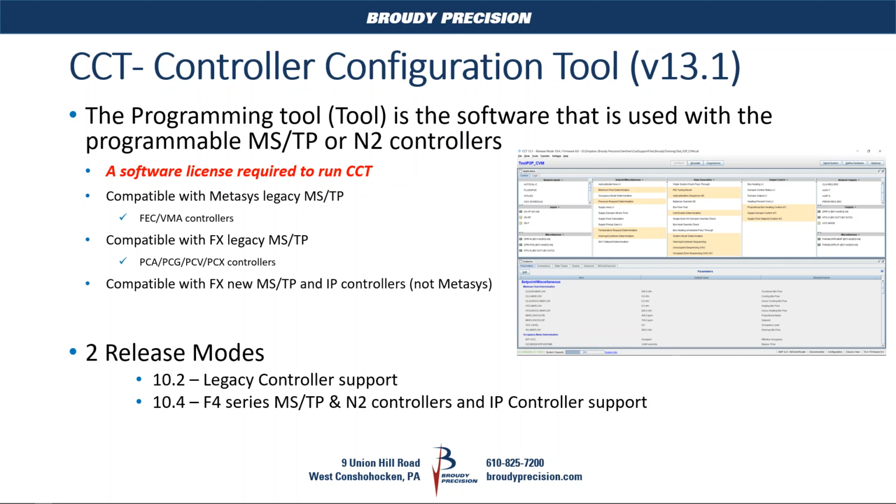The CCT tool is compatible with the Metasys Legacy MSTP controllers, specifically their FEC, FAC, VMA controller line, and also the Facility Explorer Legacy MSTP controllers, the PCA, PCG, PCV, and the PCX expansion controllers. It's also compatible with the FX new MSTP controllers, their F4 series, as well as the IP controllers. With the new series of Metasys controllers, it's not compatible. We cannot use those controllers with it, and that's all part of the licensing and how that works.